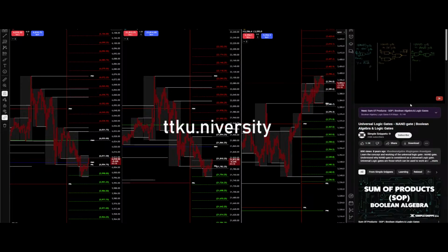Now we know that A and A is always equal to A. So this is the idempotent law, and we have studied this in the previous video tutorial. So if you have missed it, you can always check it out. So the output expression can be written as A complement only. Now notice that we supplied the value A and we got the answer as A complement. So this is the function of a NOT gate.